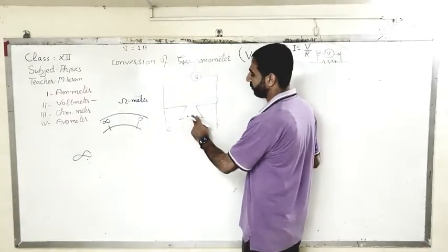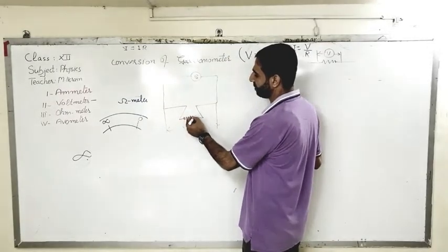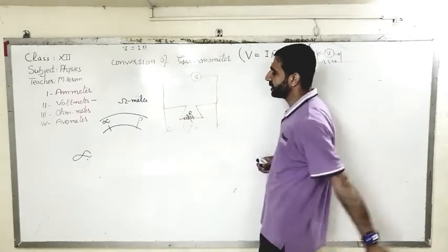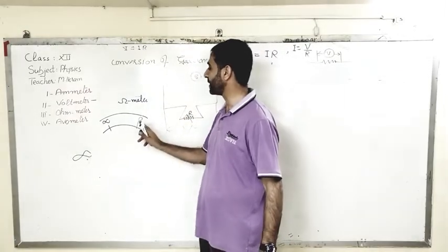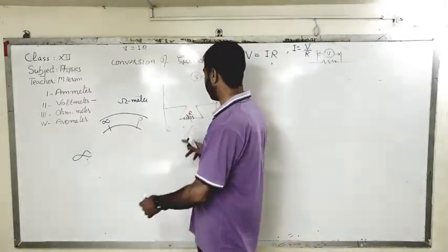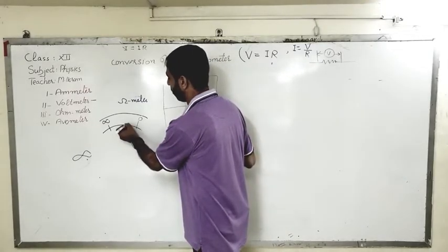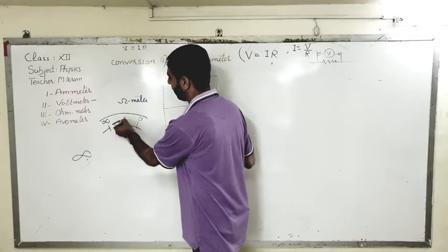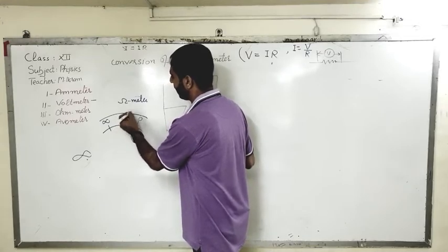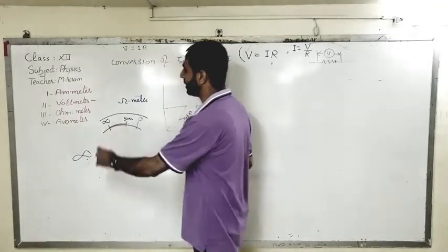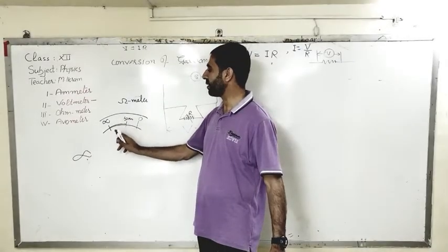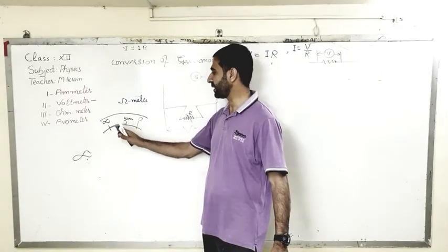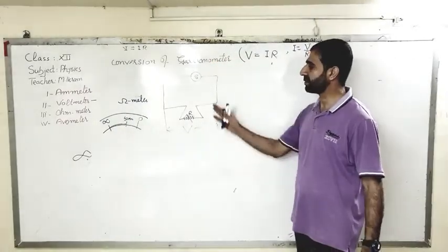Now let us do it for a known value of resistance, any resistance or variable resistance. Now if this resistance is known to me, then definitely the galvanometer needle will point somewhere between 0 and infinity. For example, if this is 50 mega ohm, the galvanometer needle will be somewhere here, and then this distance will be divided into equal parts, and then we will scale it between infinity and that maximum value. So this is very easy.